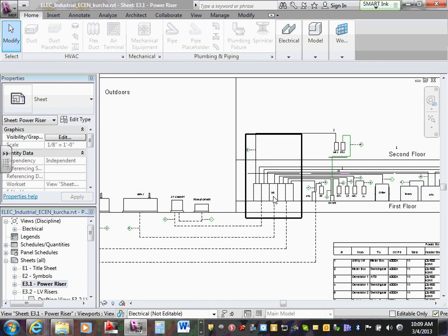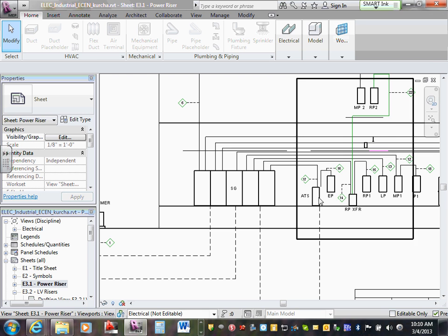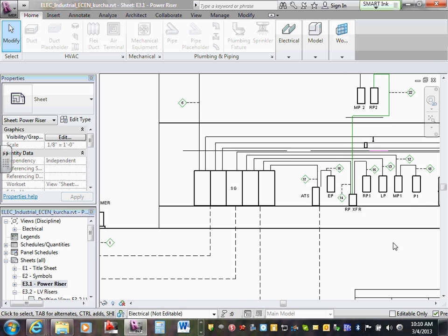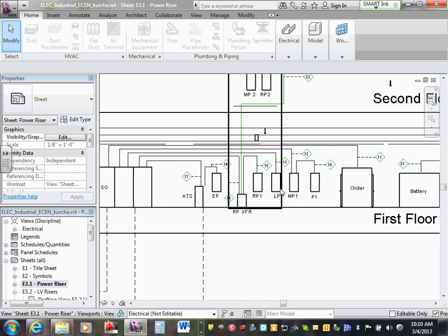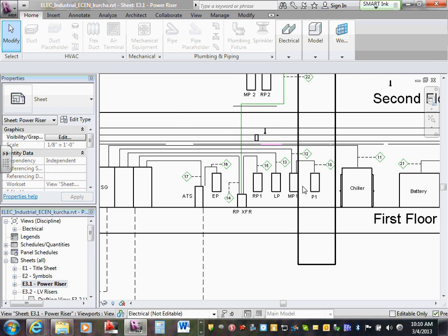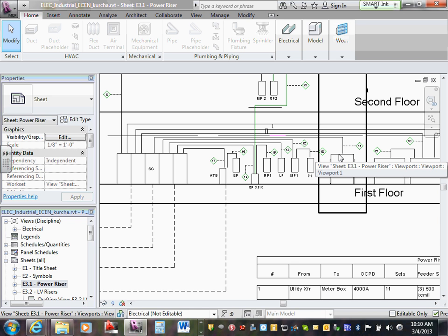The first and the most important thing in our system is the emergency panel. So the first load, step number 1, is going to be what? Your emergency load. So let's count them, by the way. I have my emergency load here. The next important things, we're going to go to UPS. So what the step means, guys, when you start your generator, we're going to turn the emergency light on first, then the UPS second, then lighting, then receptacle, then mechanical 1, then mechanical 2, then bus 1, then bus 2, in this order.